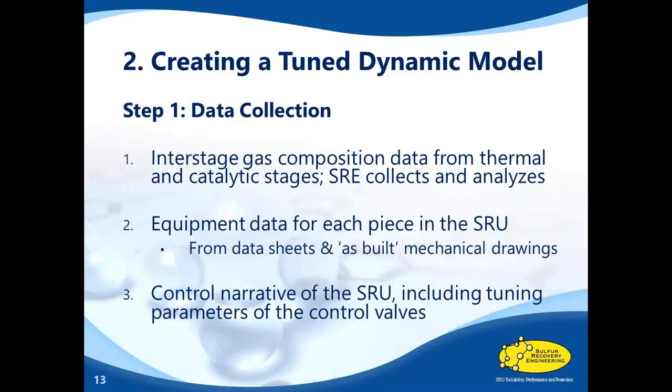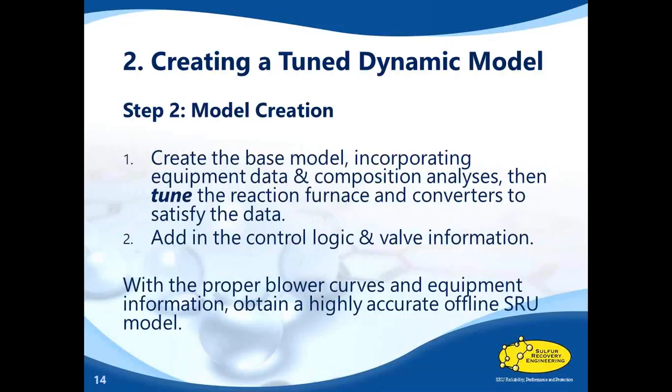Third piece of information that you need is the control narrative of the SRU, how everything is being put together, as well as the tuning parameters of the control valves. Once you've collected all the data, then you go to step number 2, which is create the model. You need to gather all the information ahead of time.